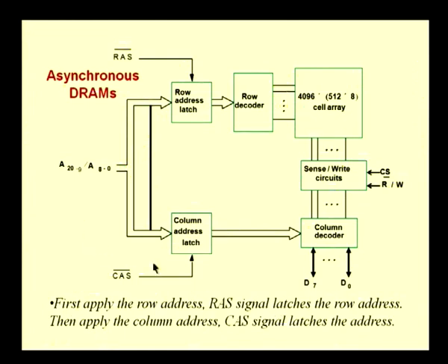Let us look at what we do there. The way we use this is that we will first select a row. The addresses themselves will come in two parts, that is, we will first send the row address and then we will use the same address lines to send the column address. Okay. So, you can see that we are actually multiplexing the address lines, because if you have a very large memory structure, the number of address lines that we require will be very large.